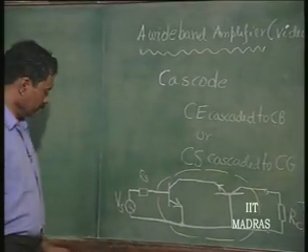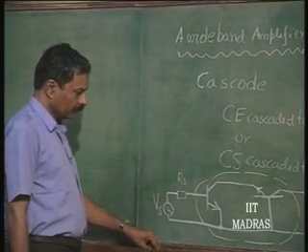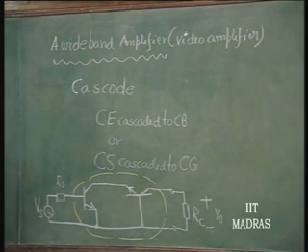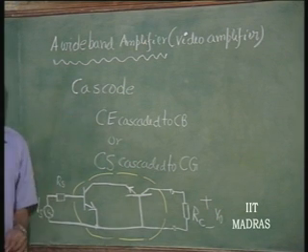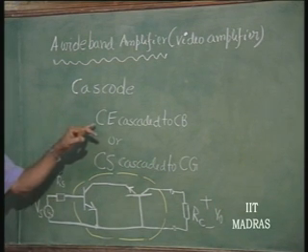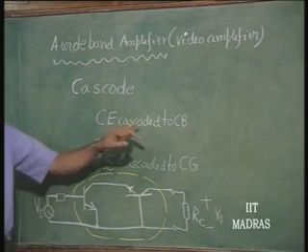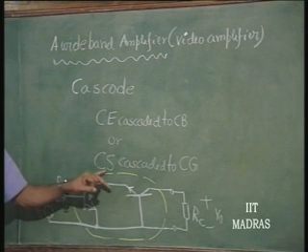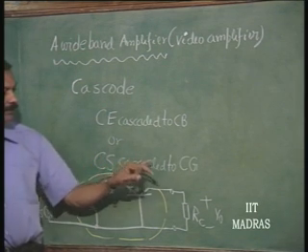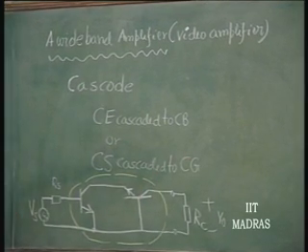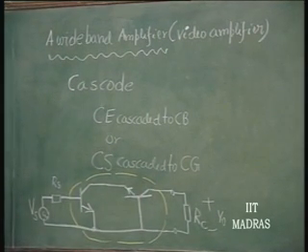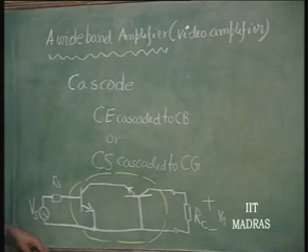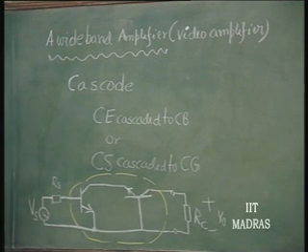So, in the last class we started discussing a wideband amplifier which is a cascode structure. A cascode you get when you cascade a common emitter amplifier to a common base amplifier, or in the FET case, a common source to a common gate. What is the virtue of this? How did we get the widebanding? Widebanding is always got in all these cascaded structures by maintaining the time constants low. Wherever time constants occur, we try to maintain these low.